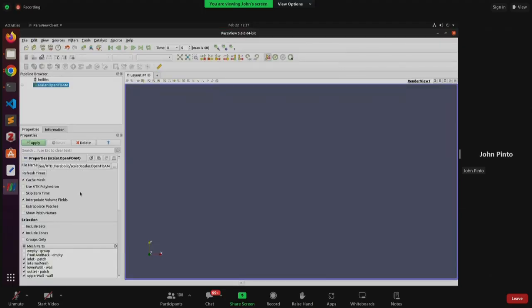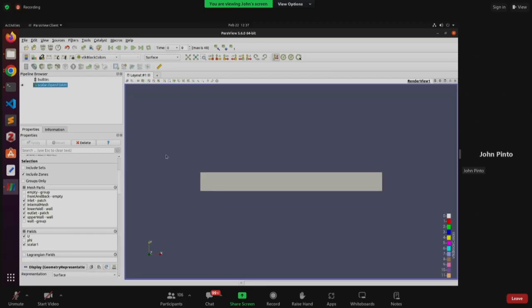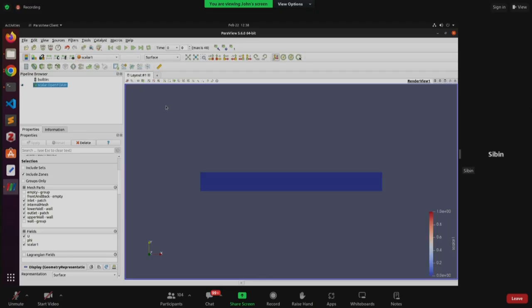Yeah, so now I will scroll down and click on scalar 1. So can you guess what will happen? Anyone? We have given a parabolic profile instead of a constant profile. Our average velocity is 1, so how will that parabolic profile be? At the center it will be 2, at the ends it will be 0. So at the outlet, will I see it at time t equal to 1 second earlier or later? Later, right? Okay. Why will I see it later? Because the walls are not moving.